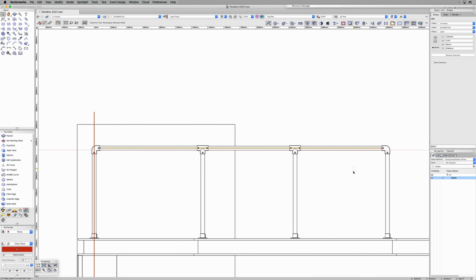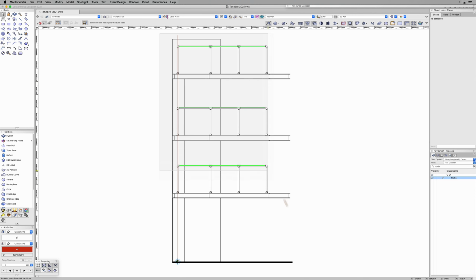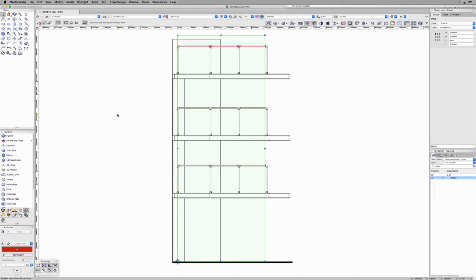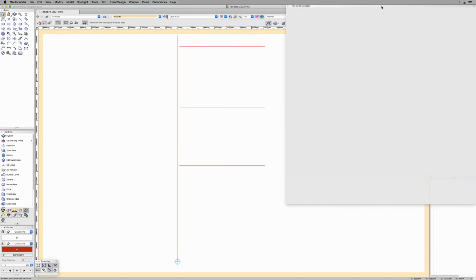When the lines are done, I select them and run the Convert to NURBS command. This will convert the 4 lines to 3D NURBS curves, and the command will place them inside a group. If I'm going to create a hanging position that I know I'll be rotating, then all the geometry must be 3D only. All I need to do now is edit the group and place a 3D only marker at the origin.